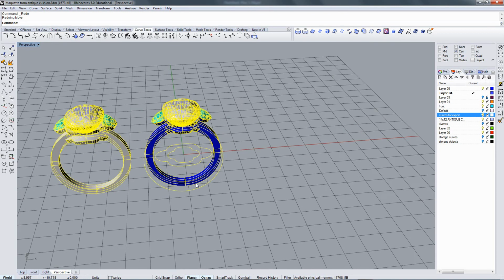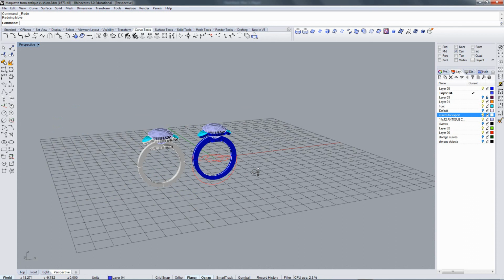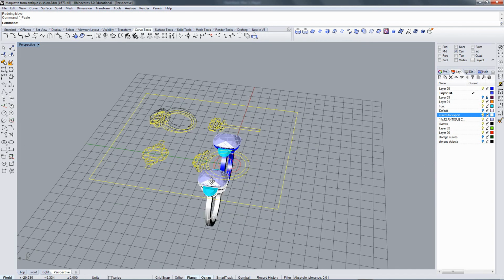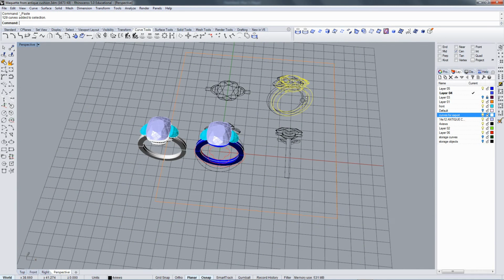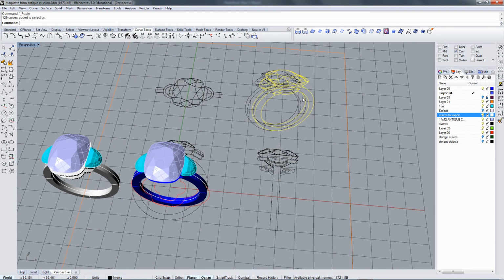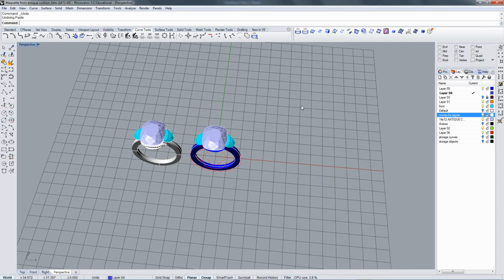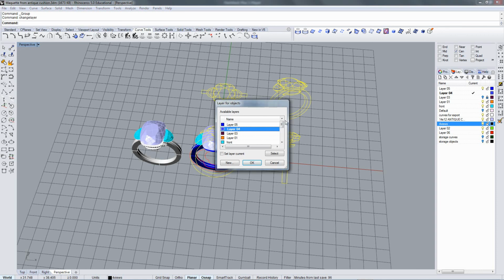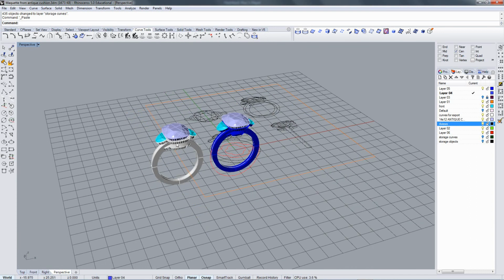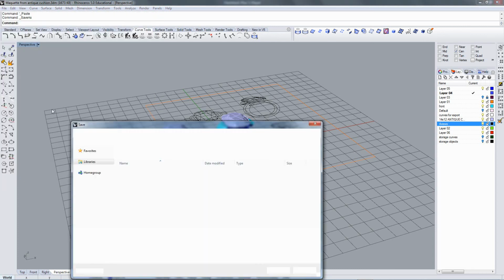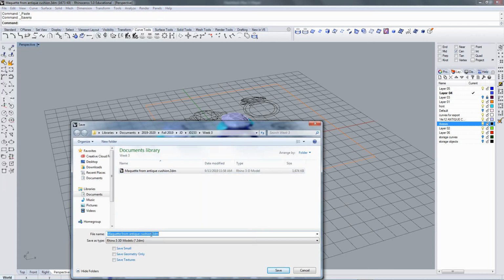And I think that's good. Paste. And now I can save my file, although I don't want to keep the original drawings in here because that's confusing. So before I paste, take these, group them and put them in storage. Then paste. The file's updated. I ended the booleaning so I can use this later. Save it. And I'll actually save as revised.